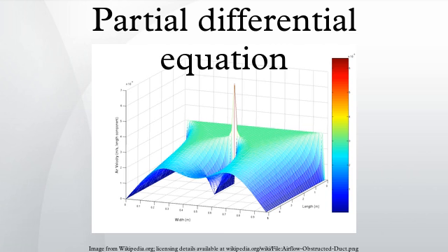In the finite volume method, surface integrals in a partial differential equation that contain a divergence term are converted to volume integrals, using the divergence theorem. These terms are then evaluated as fluxes at the surfaces of each finite volume. Because the flux entering a given volume is identical to that leaving the adjacent volume, these methods are conservative.